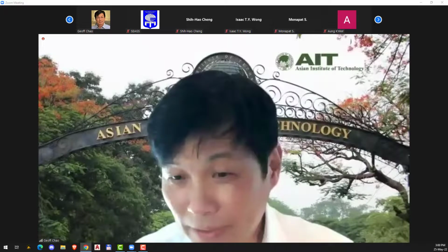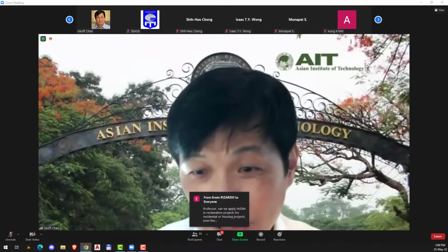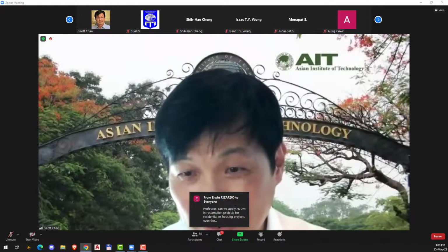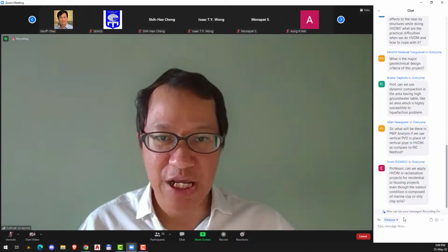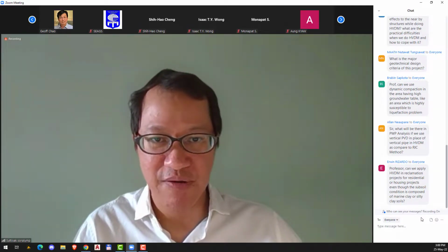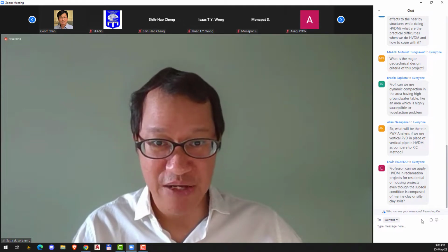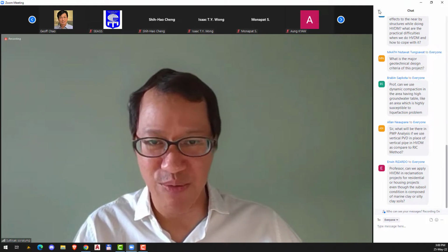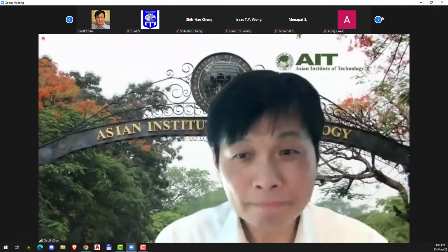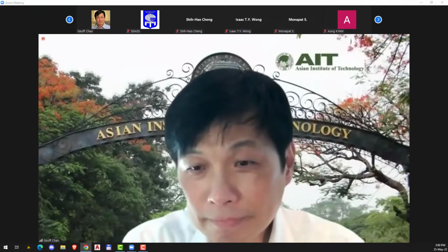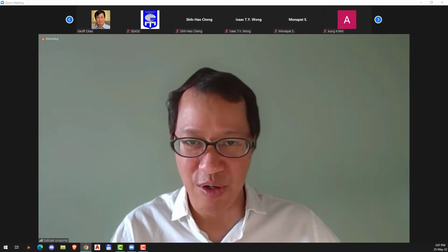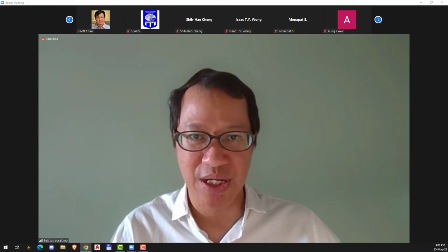Well, thank you very much. Oh wait, we got another one to see. Can we apply HVDM in a reclamation project for residential or housing projects, even though the subsoil condition is composed of marine clay and silty clay? Wow. I would not recommend it. I would recommend going directly to VCM or PVD with preloading. That would be more appropriate.